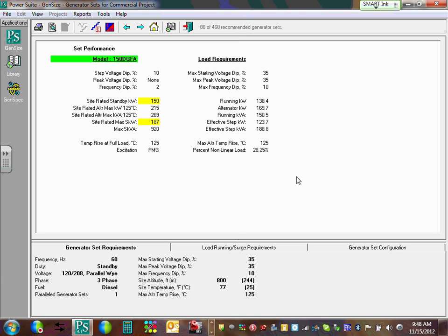When you are done, what you need to do with this number when you come up with it, guys, you're going to go put it on your Revit and size the feeders based on this number. And how do you size the feeder based on this number? This is KW divided by 0.8. It'll get you KVA. Find the amps, multiply the amps by 1.25, and size your overcurrent device and conductors. So it might be smaller than the service, which is okay. Okay? Is that enough to get your juice up and running? Cool.